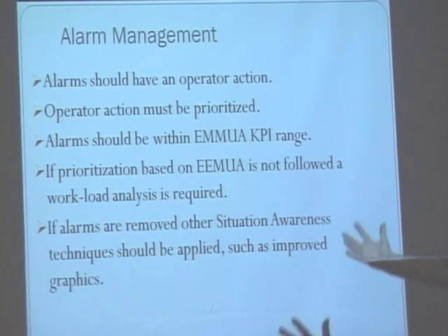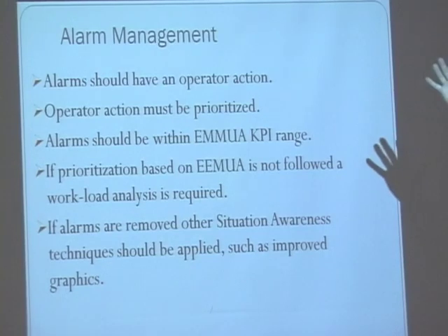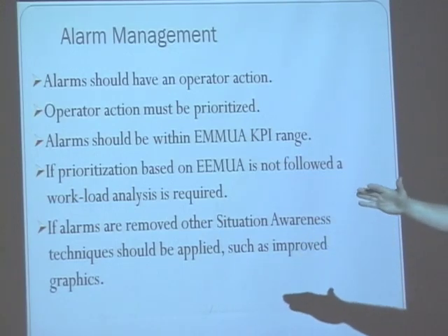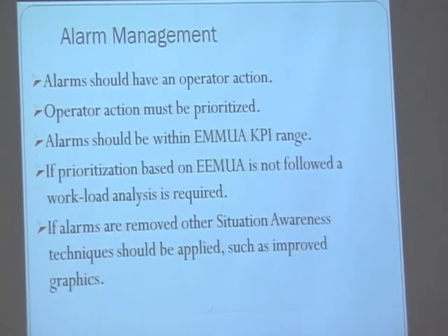Today we've loaded up the alarm system, and our dependence on the alarm system, we haven't done much with the graphics, right? So if you want to start reducing alarms, guess what you've got to do? You've got to start making improvements so operators can detect things through the graphic system.